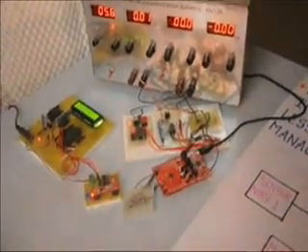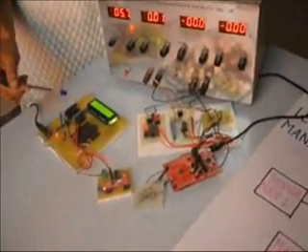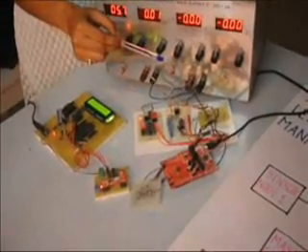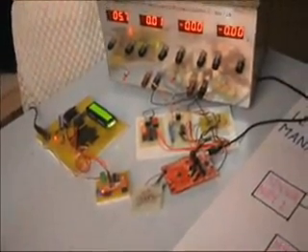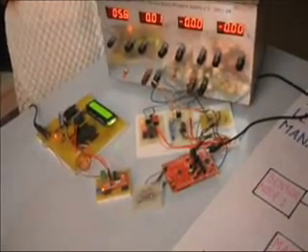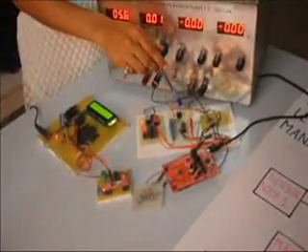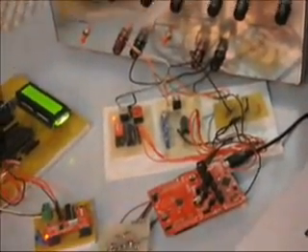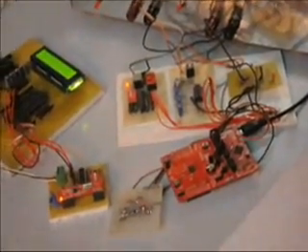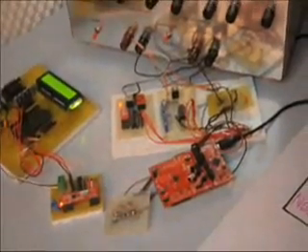Now at the receiver side, the master receives the signal, the output of the INA138 in the form of voltage. This output needs to be converted into current using a formula. The output voltage is further given to the LM324, which is used as a comparator. As we have set the reference voltage for the comparator, when the load increases above the reference voltage, the output of the comparator is high.